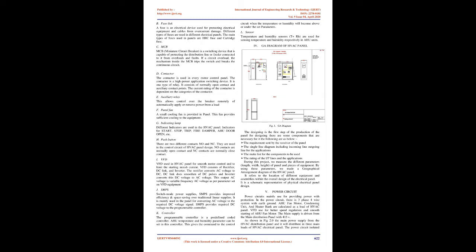C. MCB. MCB, miniature circuit breaker, is a switching device that is capable of protecting the distribution line or feeder connected to it from overloads and faults. If a circuit overloads, the mechanism inside the MCB trips the switch and breaks the continuous circuit.